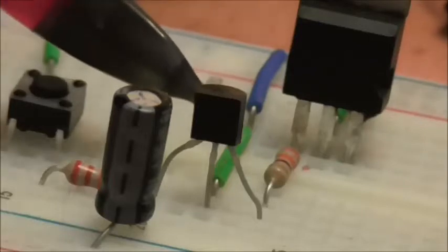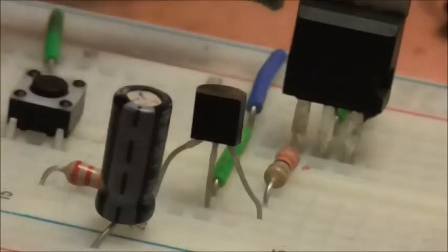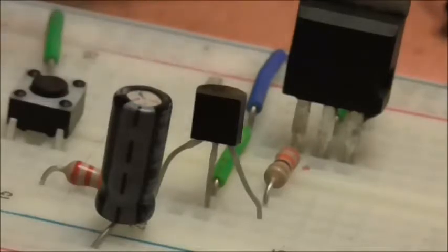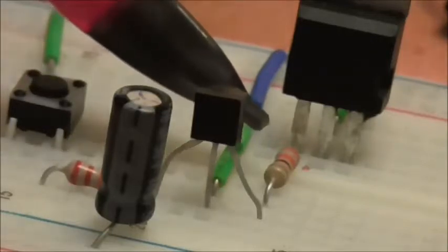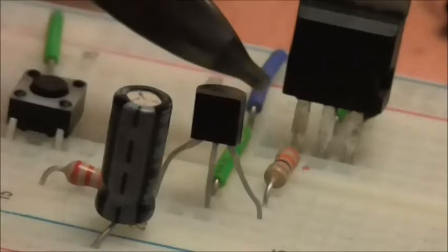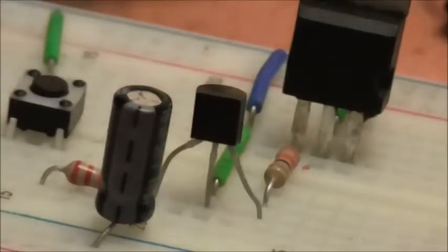The anode of the thyristor has been hooked directly into the 9-volt rail, and coming from the cathode we have a 330 ohm resistor going to the base of the NPN transistor. Let's zoom back a little bit